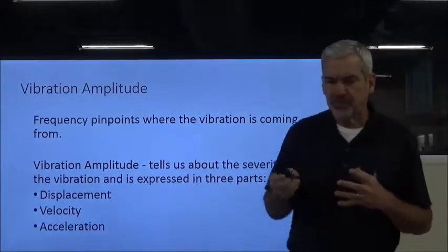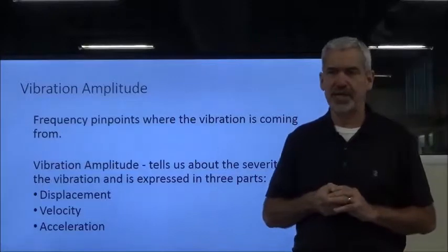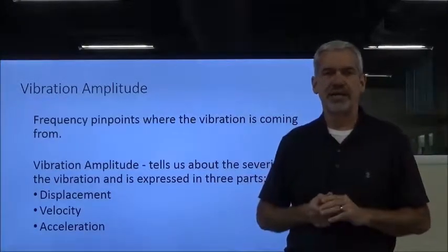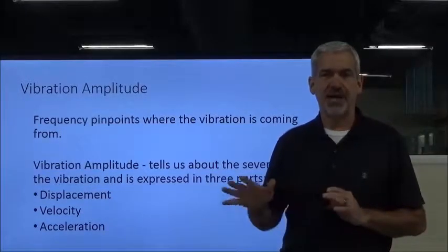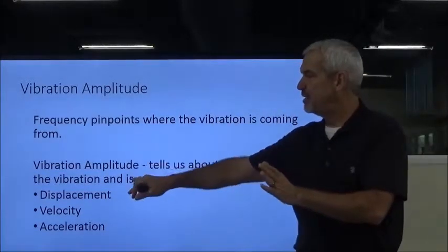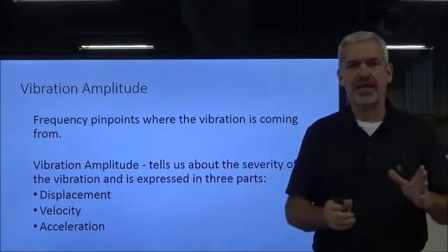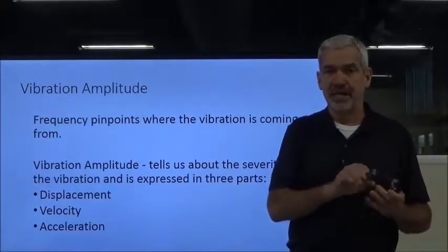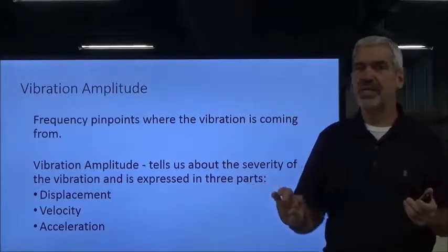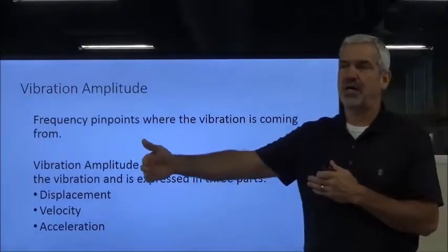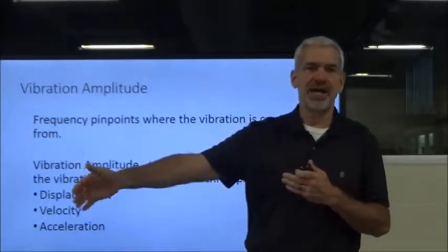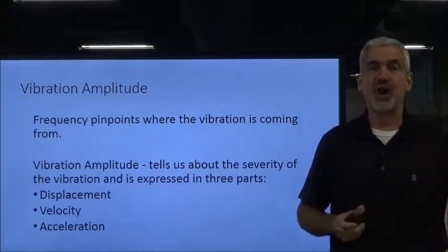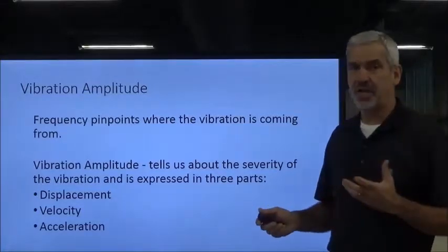For example, we may have a blower fan that's used in the process, but some vibration in that fan is okay. It can be fine. However, if we took that same amplitude of vibration and it was coming out of, say, a lathe or a mill that's used to make very, very precise products, it's completely unacceptable. So whereas one machine might be fine with a certain amount of vibration displacement or amplitude, it may be catastrophic for something else, okay?